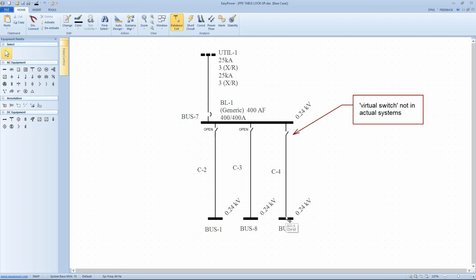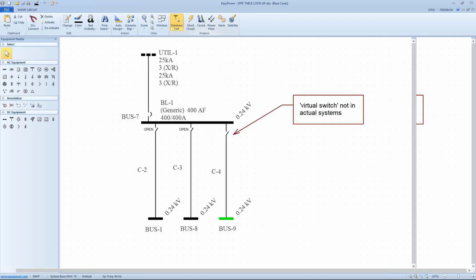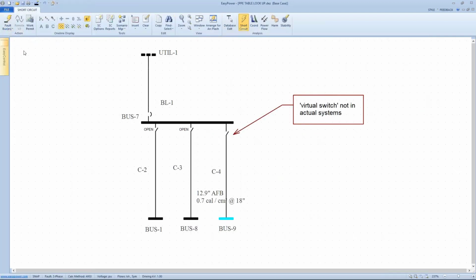And if they looked at the short circuit currents available, they found that invariably the typical amount was in the 23 to 25,000 amp range. And given that each of these panels was supplied by a molded case circuit breaker, calculating the incident energy there would give them, almost invariably, something less than 1.2 calories per square centimeter.